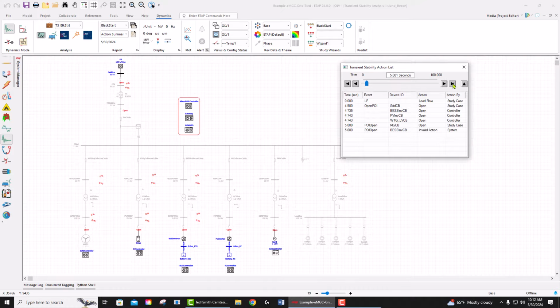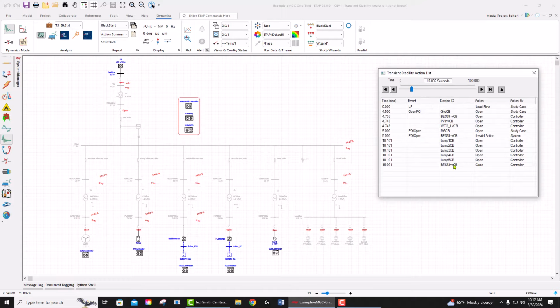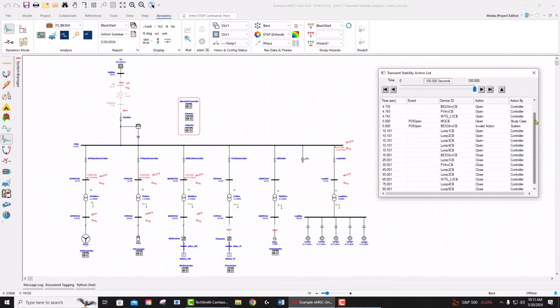And then the microgrid controller detects that the system is black, is going to make sure that all the loads are disconnected, all the assets are de-energized, and then the black start starts. And in this scenario, what the microgrid controller is going to do is energize the battery. As it energizes the battery, it's going to bring all the assets and the loads in a proper order to make sure that the voltage and frequencies are within acceptable range. It brings all the loads one at a time, and then renewables one at a time, and it energizes the system, and the system becomes energized.